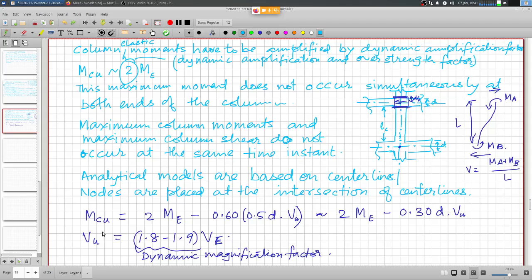But generally it is better not to allow any inelastic deformation to take place except at the bottom of the columns at the ground floor support levels. That is where there is no other element to dissipate energy, and the columns have to develop hinges, and appropriately you need to account for ductile detailing, so that large curvature ductility can be achieved at the bottom end.